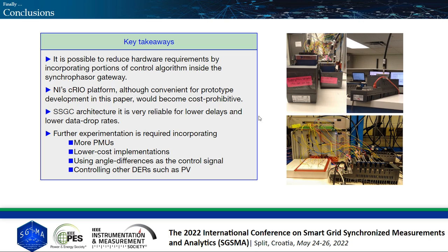So, what are the takeaways from this presentation? First, it is possible to reduce hardware requirements by incorporating portions of the control algorithm inside our proposed synchrophasor gateway. The compactRIO platform which we used for our implementation, even though it's easy and convenient to prototype on, is expensive and needs to be migrated to a different platform. For lower delays and lower data drop rates, our architecture is very reliable.